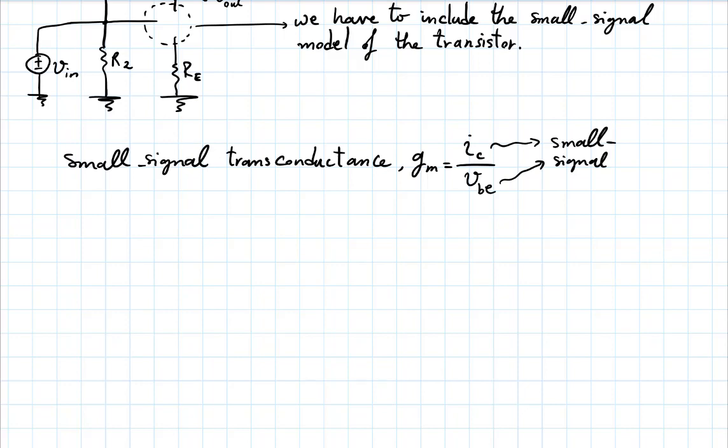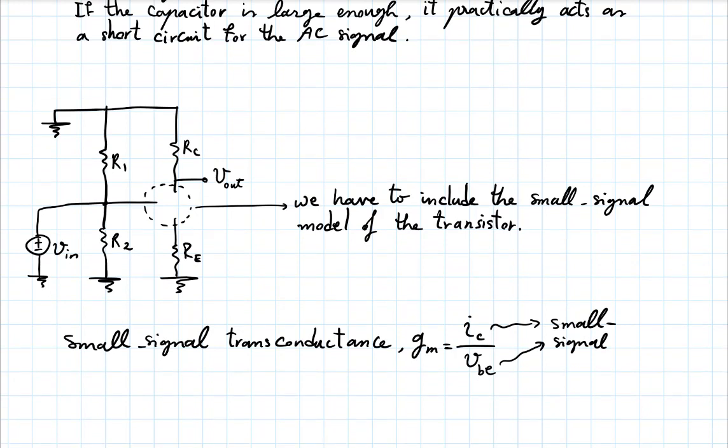What we saw last time, and talked about at the beginning of today, was that in small signal you are approximating the behavior of the device with a linear behavior, and you're saying the ratio of the output to input is basically a constant, as long as both input and output are small.